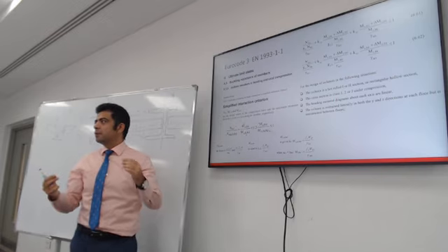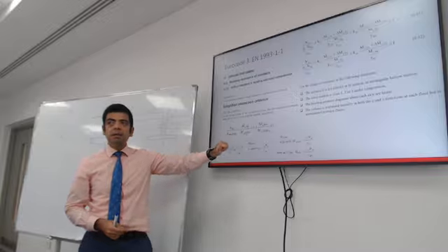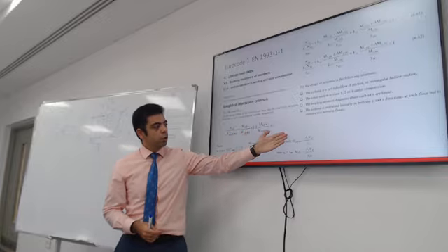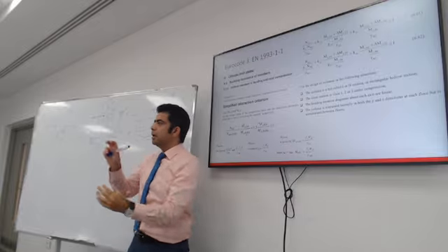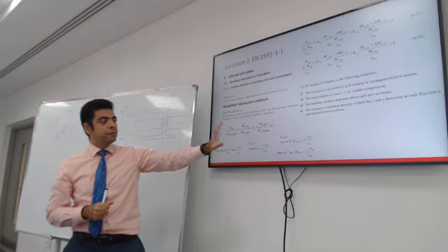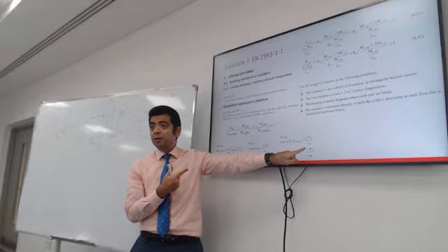So you will consider the lateral torsion buckling in the direction about y, or in the strong direction. In the weak direction, you will just consider the moment capacity of the section. These factors we've dealt with in the moment capacity lecture.